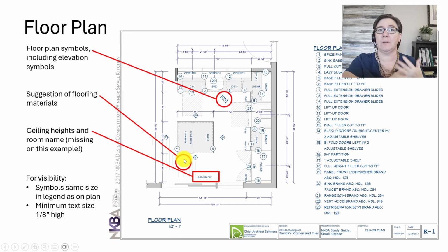We don't want you to completely tile the floor with a hatch showing the flooring because it gets really busy and starts to be confusing. Instead, when you're close to done drafting, find an area on your floor plan that is less crowded, shall we say. And in that area, show us kind of a suggestion of that flooring. The whole point here is to show the direction and how it should be installed. All right. Now, missing on this set, that flooring should be listed in the specification and then go ahead and tag that specification right where your hatch is.